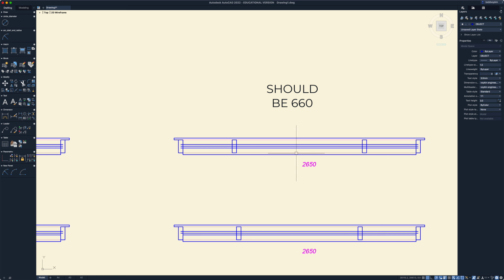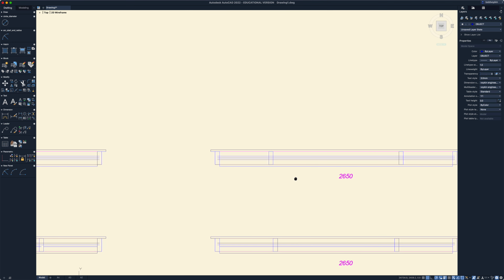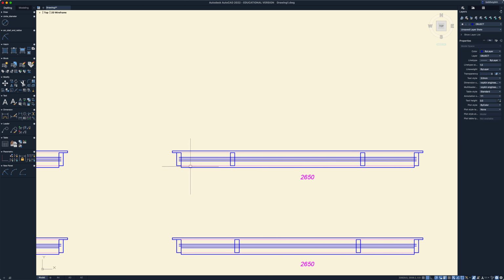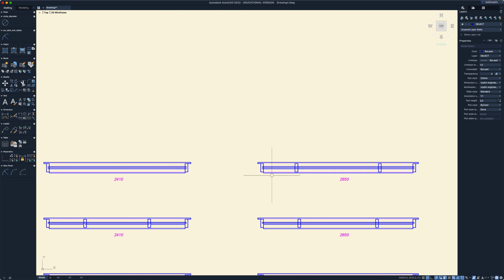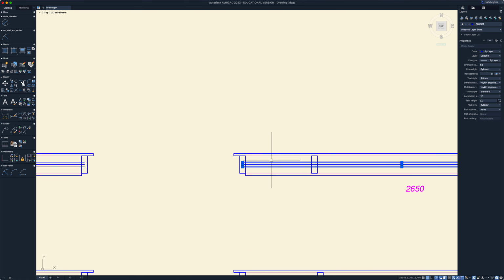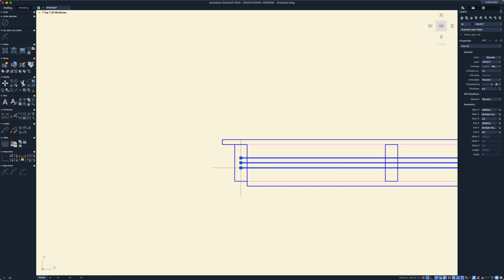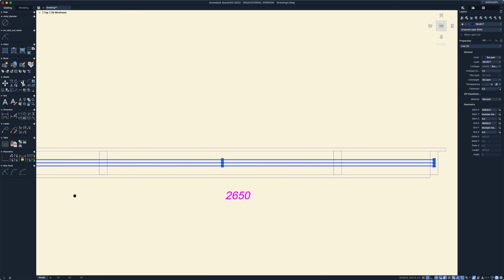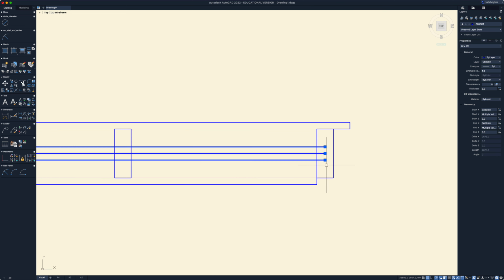And with this one, that piece in the middle is definitely getting too big, so this one is the double hung, so I'd be going like this, grabbing those three grip points, moving it over to here. Come on. I do the same thing on the very far side.